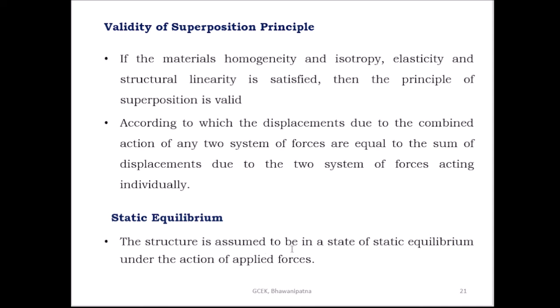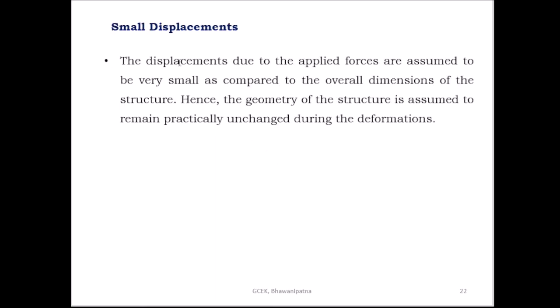The structure is assumed to be in static equilibrium under the action of applied forces. And this is also one assumption: small displacements. The displacements due to the applied forces are assumed to be very small as compared to the overall dimensions of the structure. Hence, the geometry of the structure is assumed to remain practically unchanged during the deformations. These are the assumptions which are considered for the analysis of skeletal structures.